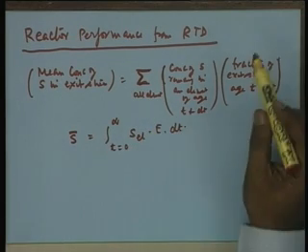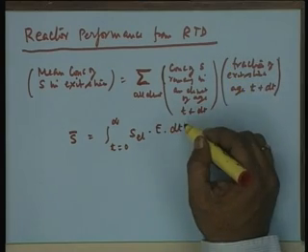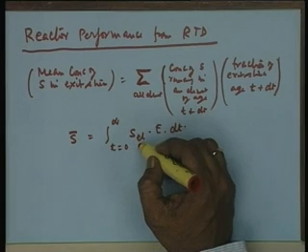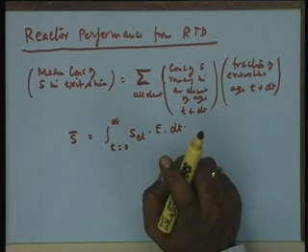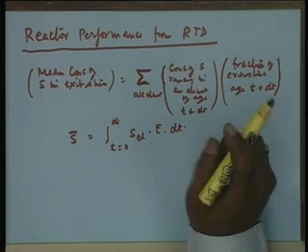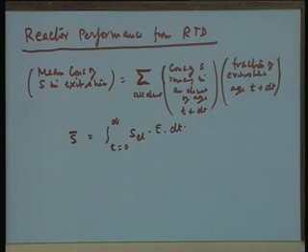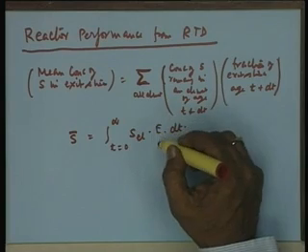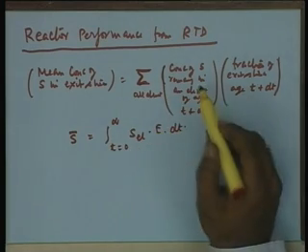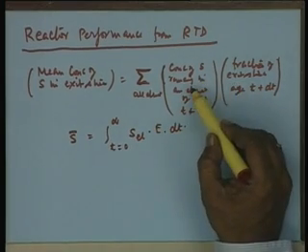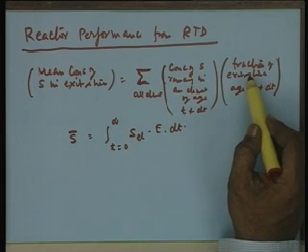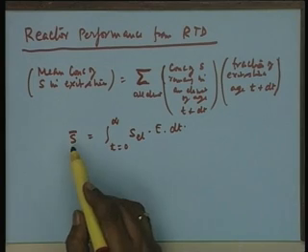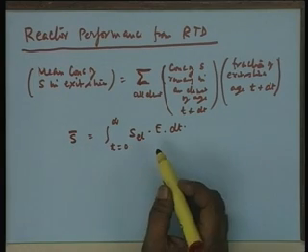Basically, E dt is the fraction of the stream, and S element is the concentration of substrate remaining in the element which is of age t plus delta t. Now these two terms indicate the concentration term as well as the age term in the reactor, and essentially the mean substrate concentration in the reactor will be given by this.